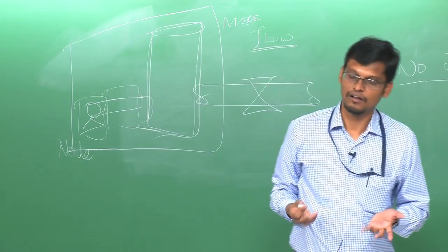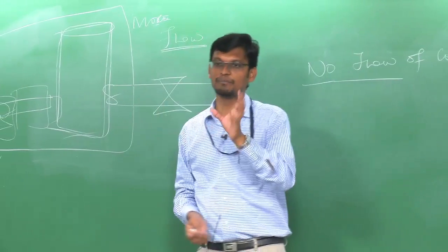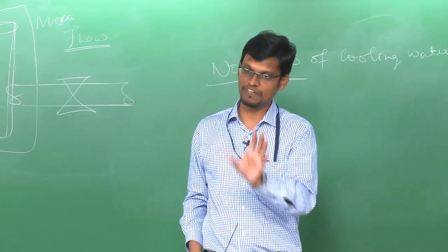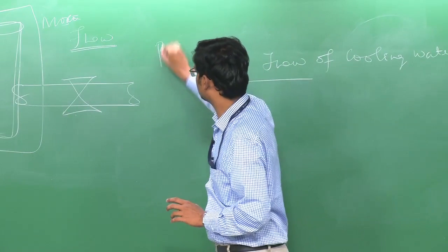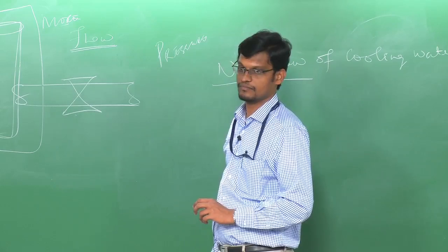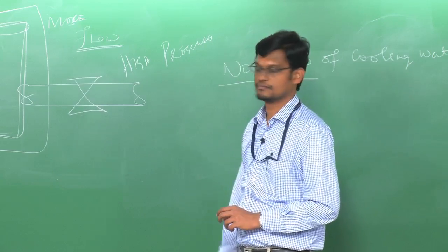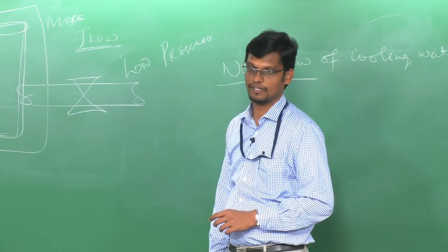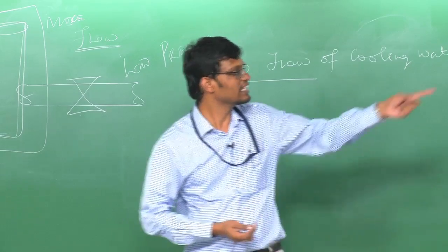Valve malfunction, meaning, see what happens here, the moment you start doing it you will understand it is purely dependent on the design intent. If my design intent itself is to keep the valve half open, then accordingly you will discuss. Same thing applies to pressure. Okay. Now what happens? So, that is what you try to do with a set of parameters, and that is what the deviation is all about.